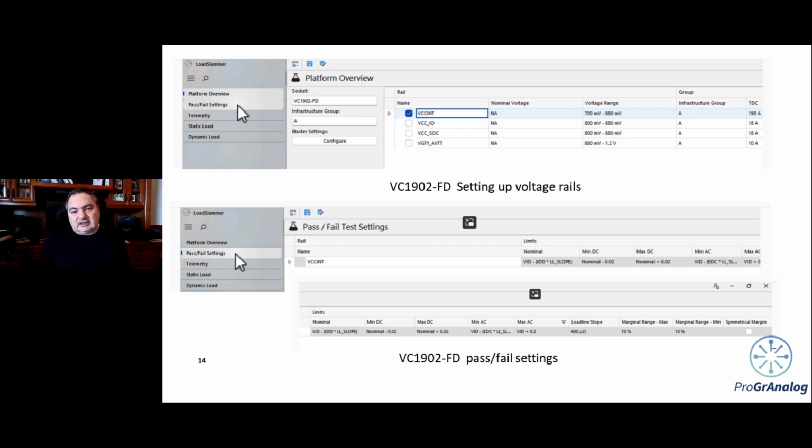This is really where the test engineer leaves. With Xilinx, you would have your PDM, the Power Design Manager tool, and that would tell you, like it did in a previous slide, how much current you can expect to be pulling from the device, given the amount of utilization and clock frequencies, etc., that you're going to target the fabric with. That's a conversation you have with your Verilog system engineers. Here's where you enter those coordinates into our tool, and this is where it sets the pass and fail and the margin criteria.